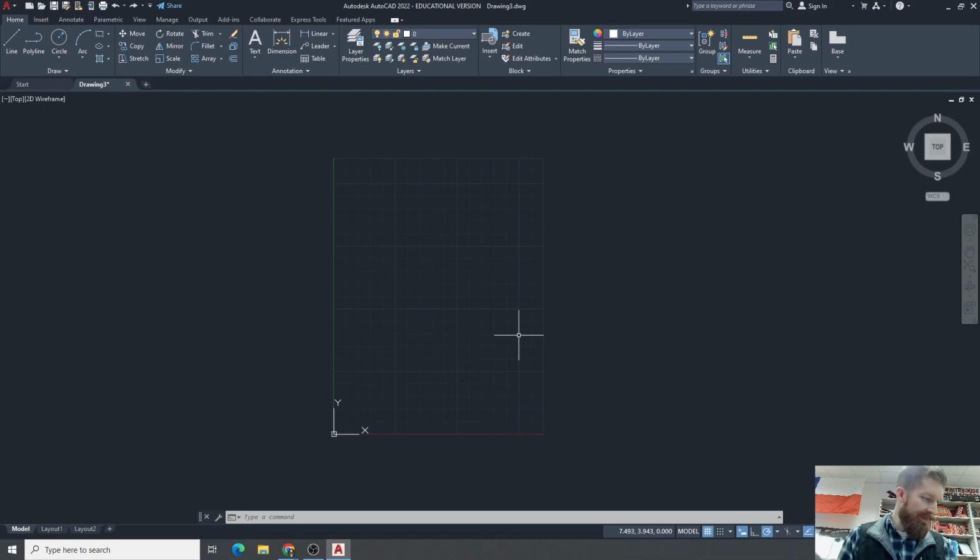If you plan to plot from a layout, limits in paper space should be set to the actual paper size. However, setting the paper space limits values is automatically done for you when you select a plot device and paper size from your page setup. So what I just did here would be done automatically if we went through the page setup route.